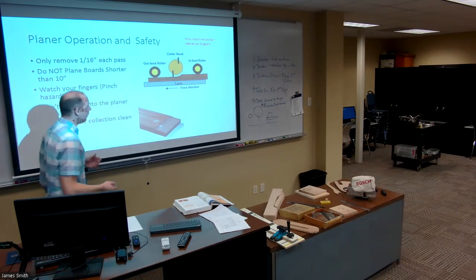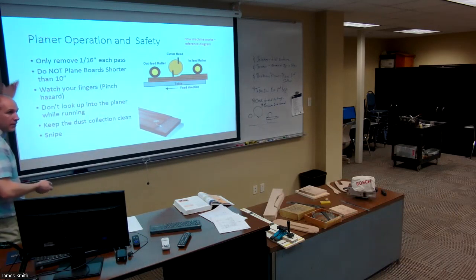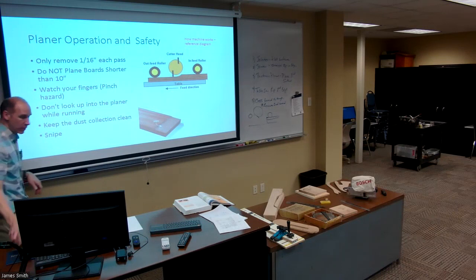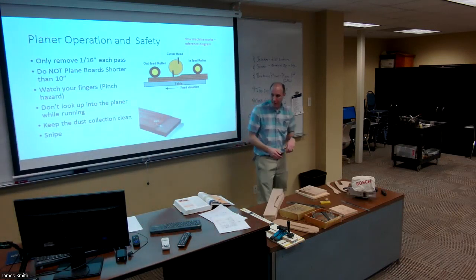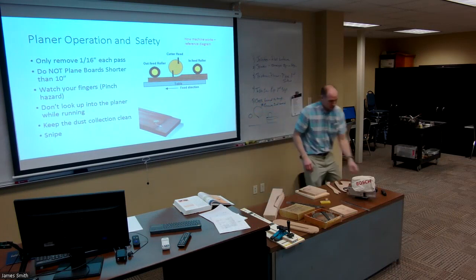How do you avoid that? Well, you just put a little bit of pressure up. Help support the board when it's going through the planer, and then you won't have to deal with it. Okay, and so that's what's nice.